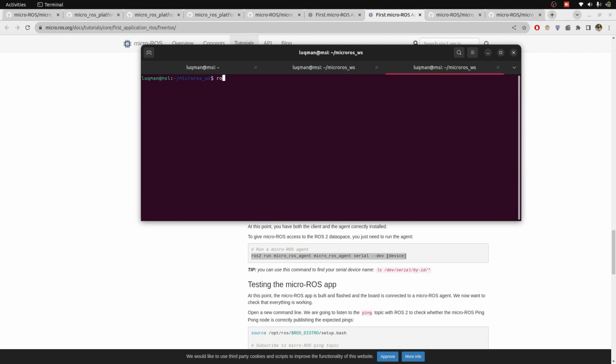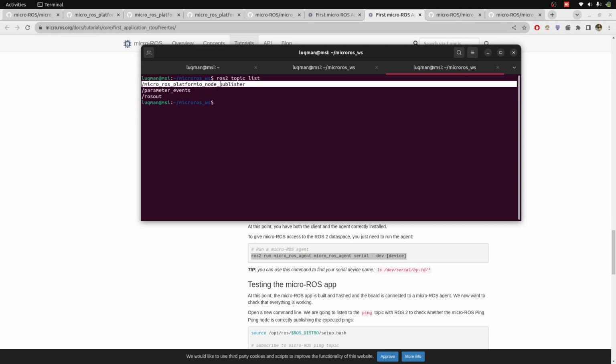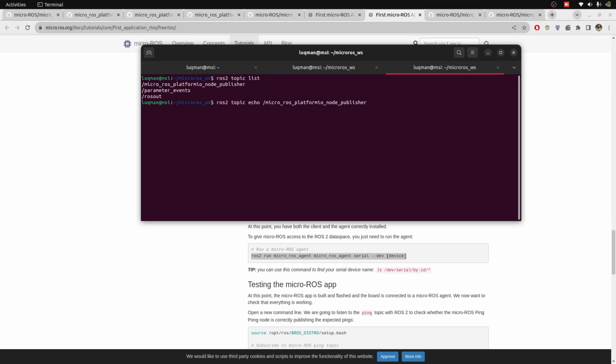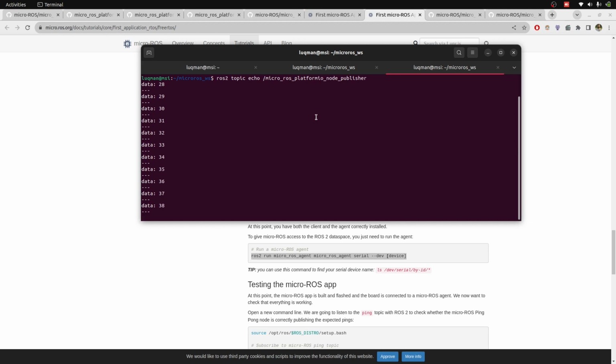Let's clear these. ros2 topic list. And this example MicroRos PlatformIO node publisher is here. Let's perform ros2 topic echo. What does it publish? It is a counter that is publishing things. So in a nutshell, our whole MicroRos making ESP32 communicate serially right now has been completed.